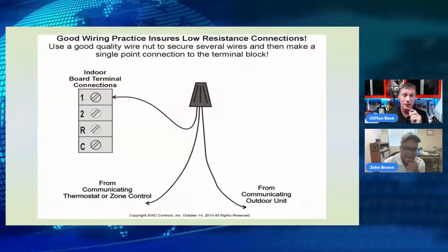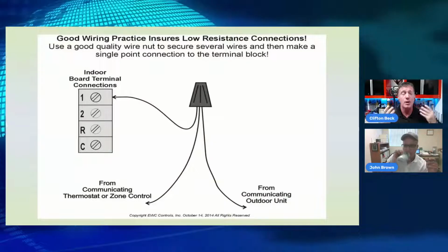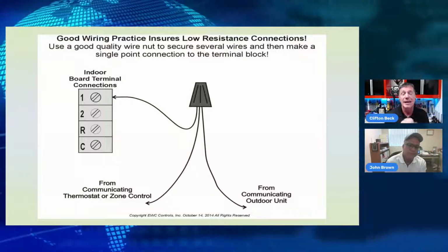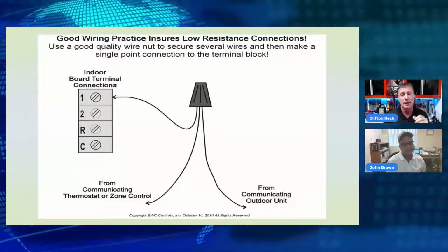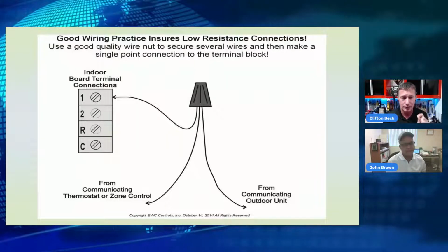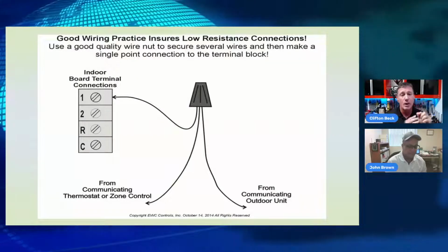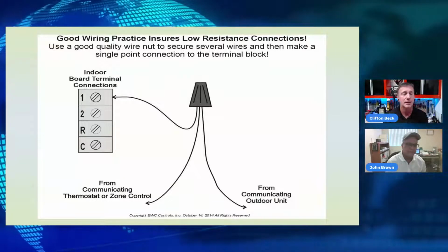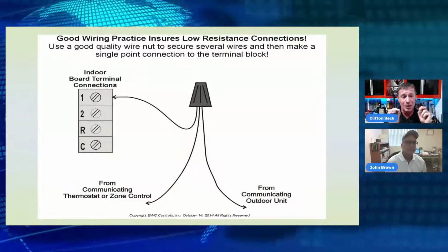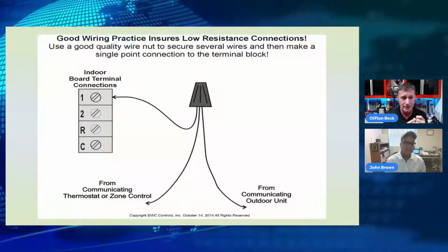It is, John. One of the things that I had encountered with this exact same scenario is many a time with original solid conductor control wire. Because we know if the application allows, technicians are going to flush a line set, they're going to reuse the original conductors, and it is acceptable if things are installed properly. One of the things we have to understand is with that solid wire conductor, it might have passed current through properly on an AC load. Because remember, our legacy thermostats had a switch and we were applying a load through that conductor for our thermostat wire. Now, when we get to work with our communicating systems where we're talking about a different impedance and a low amount of current passing through the wire, if we have a lot of corrosion on that wire, it is not going to make a solid connection.